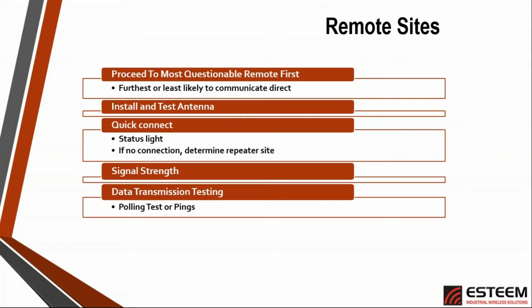Measuring the signal strength can be done one of many different ways depending upon the radio, and we will cover the specifics of how that's done by radio in future chapters of the system. Most of the time, that signal strength, especially in our wireless Ethernet radios, is all reported from the radio itself. You open up the radio's web page, and from there you can go into the wireless status, and the radio itself will tell you how much signal it's receiving across that band.